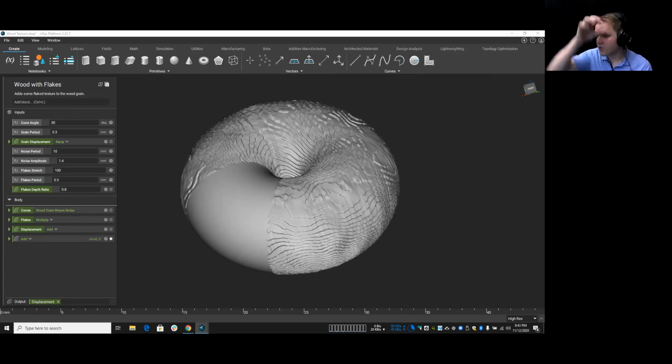Yeah, so, okay, I think it says here, can you integrate the manufacturing parameters specific to the process, SLM, EBM, into the optimization process? Depending on the powder and machine, input limits result in failed prints, thermal distortions, etc. So, does my topology optimization say, okay, I'm doing this for an SLM machine with these process parameters? No, it doesn't do that because we're not doing print process simulation at the same time. That's a very complex simulation that nobody directly incorporates into topology optimization, at least not today.